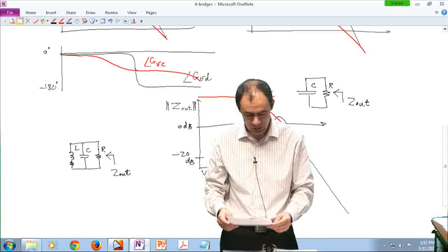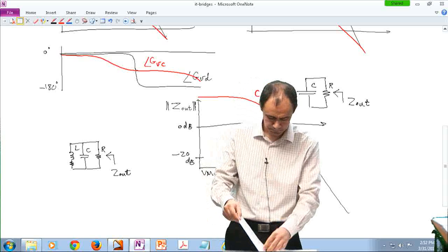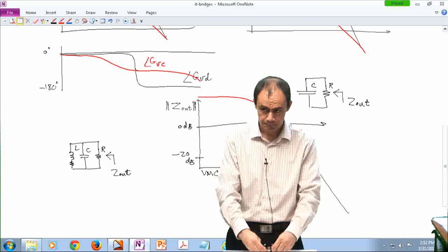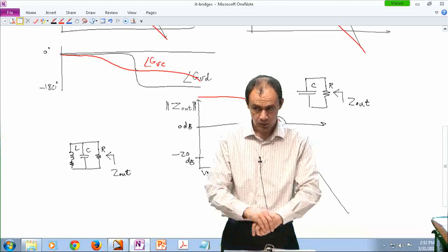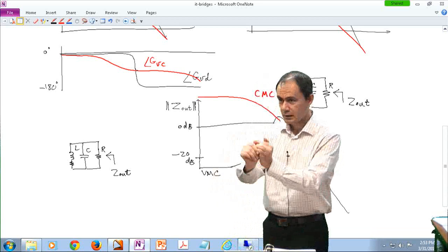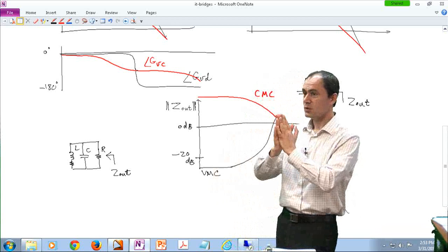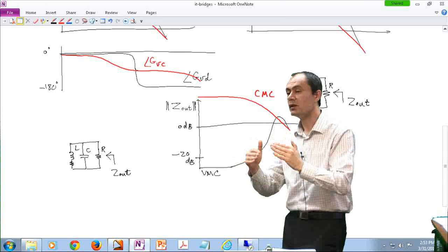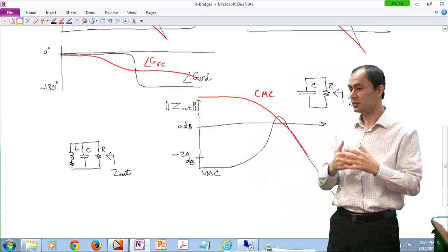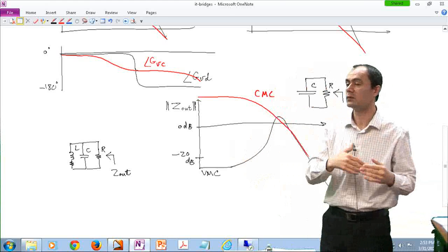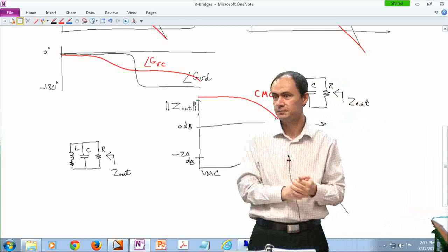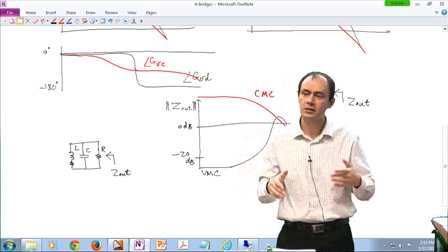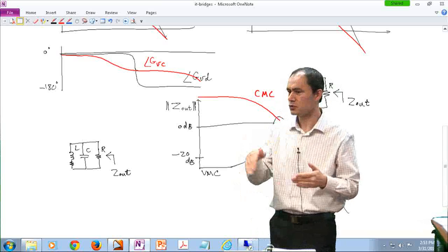All right. Any questions? Yes. At low frequencies for current mode control, we would have 1 over SC. Okay. So 1 over SC is basically infinity. Yes, but that infinity is in parallel. So we have a large impedance, the impedance of the capacitor, in parallel with the resistor. And the resistor is the dominating one, so only the resistor shows itself. Remember, DC current doesn't flow through the cap, so it goes through the resistor.